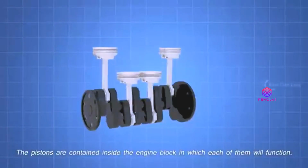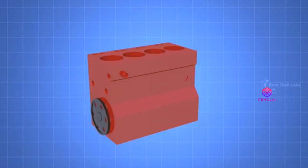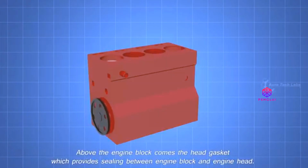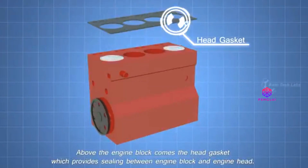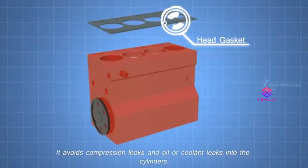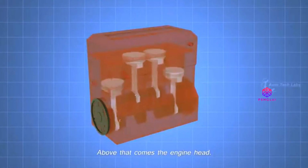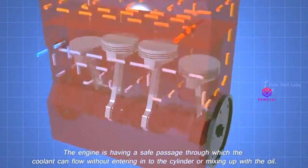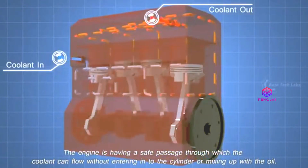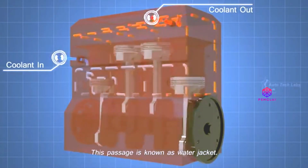The pistons are contained inside the engine block, in which each of them will function. Above the engine block comes the head gasket, which provides sealing between the engine block and engine head. It avoids compression leaks, and oil or coolant leaks into the cylinders. Above that comes the engine head. The engine has a safe passage through which the coolant can flow without entering the cylinder or mixing up with the oil. This passage is known as the water jacket.